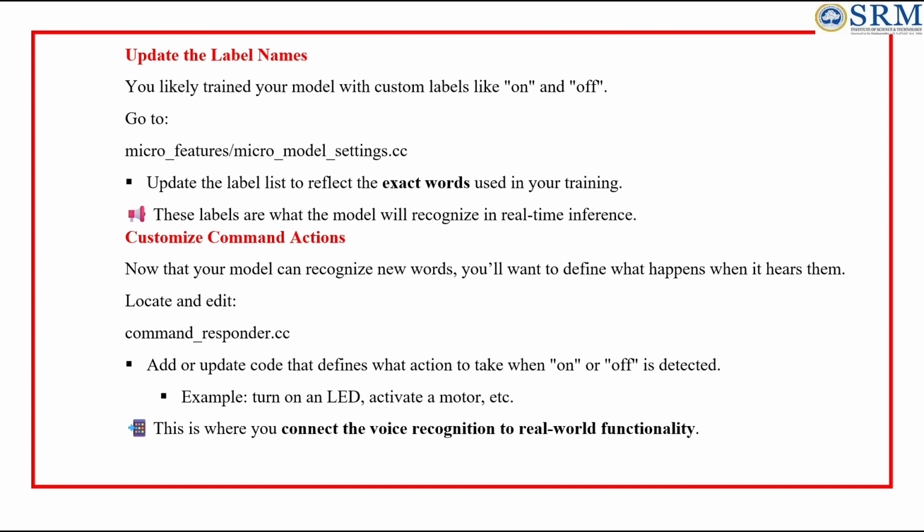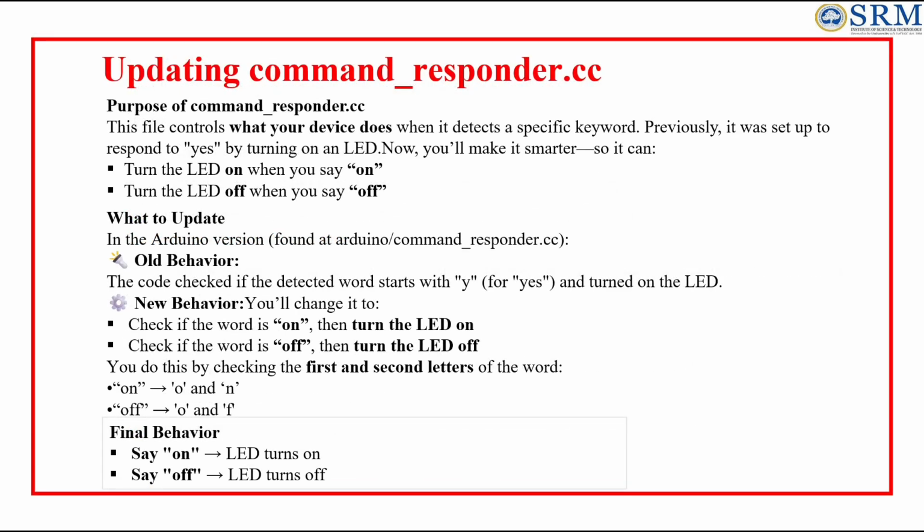This is where you connect the voice recognition to real-world functionality. Next, we will see about updating command_responder.cc. Purpose of command_responder.cc: this file controls what your device does when it detects specific keywords. Previously, it was set up to respond to yes by turning on the LED. Now it will be made smarter so it can turn the LED on when you say on, and turn the LED off when you say off.